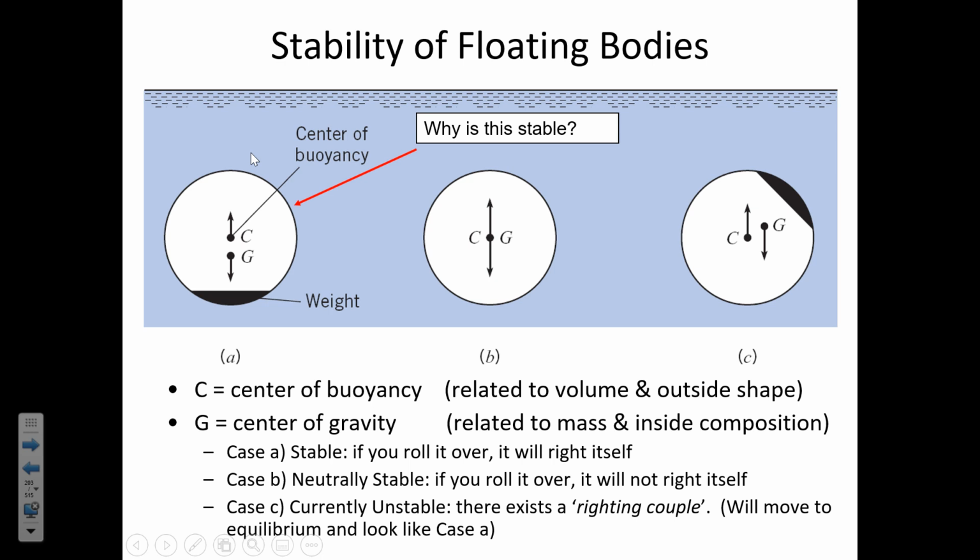So that is true. But what I didn't say is only if. Because there are other cases where you can have stability. So this is just one situation where stability can be achieved, but there are others as well. And so I'm going to tell you about that other case where there's also stability. But this is the simplest case. It'll definitely be stable if the center of gravity is below the center of buoyancy.